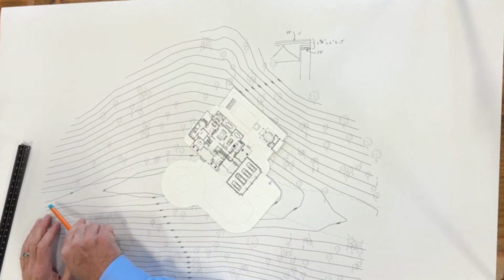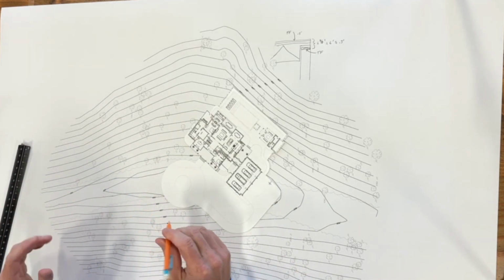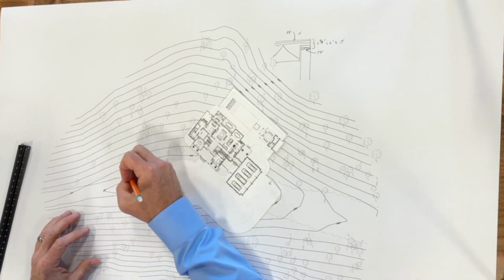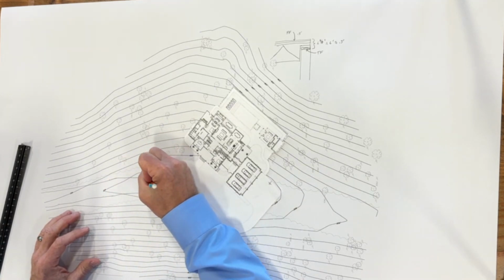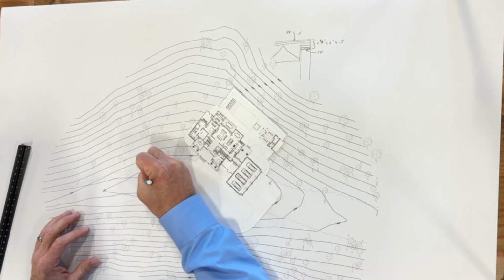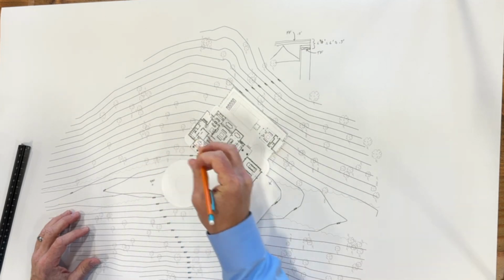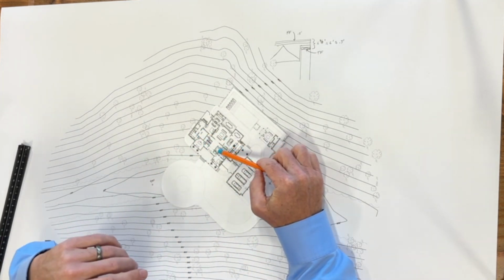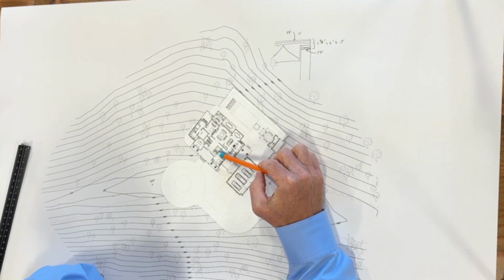So, okay. So then what we do is we say, all right, the top of foundation. Now, as we're pulling in this driveway, what I think about is, okay, what are you going to see? Someone coming in is basically going to be hitting roughly about here, about a 940. So, for instance, you wouldn't want this house at like a 935, because then it'd look like it was down in the hole, right? And you wouldn't want it at a 950, because then it'd just be ridiculously high out of the ground.